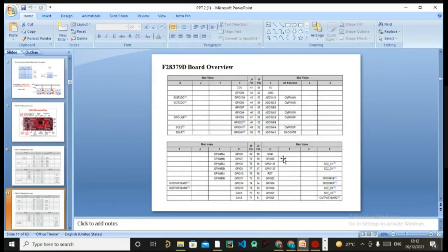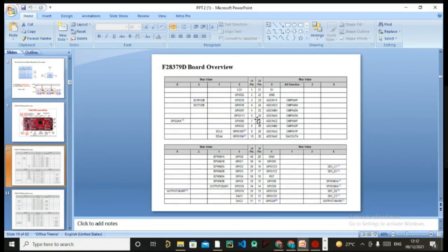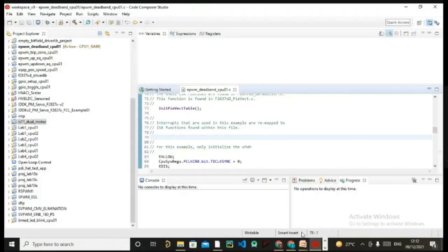from this one you can see, okay, that is not available to you. So certain pins are available to you, certain pins are not available to you. So whatever pins are available to you that you can use. Yeah, GPIO 19 and 18 is here. From this one you can see J1 pin number 3 and J1 pin number 4. So for 19 and 18,